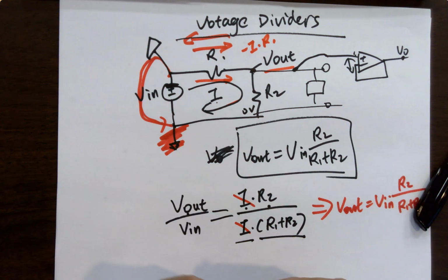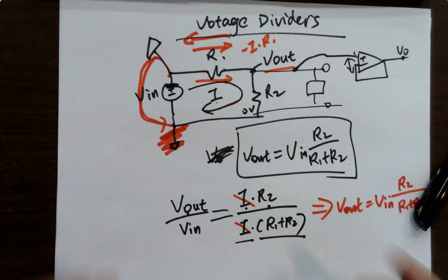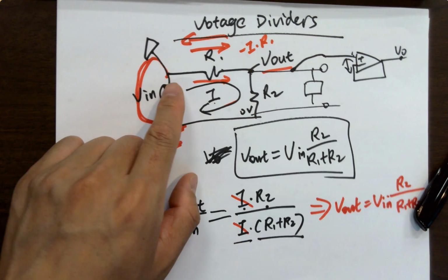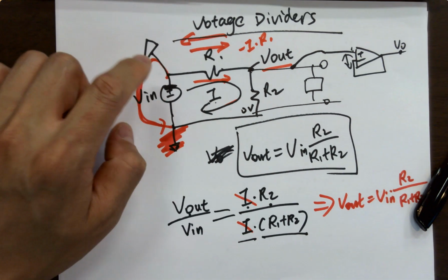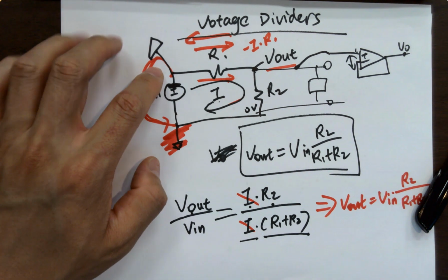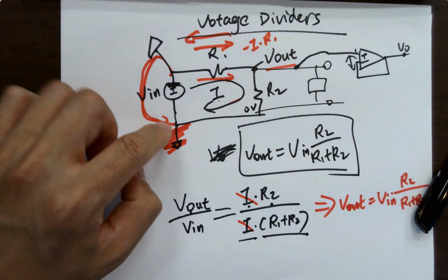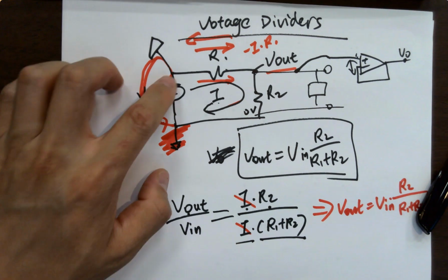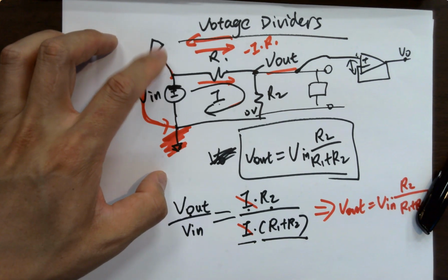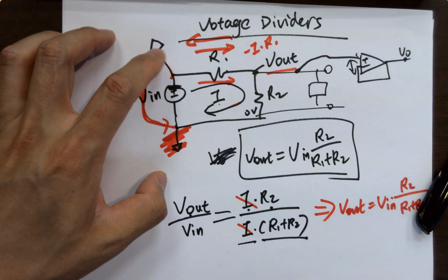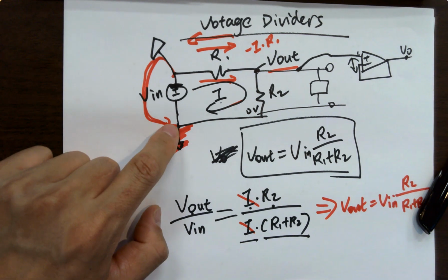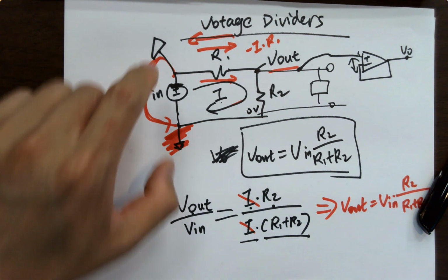Is that confusing? Is it confusing for everyone? Ignore the power source for now. If I ground this power anode, so I grounded the cathode, right? I ground the cathode. Why can I ground the anode? I'm just supplying a negative voltage. It's okay. I ground the anode. What's the voltage here? Is it still Vin? Isn't it negative Vin? It's not negative Vin. I ground it. I told you I ground it. What's the voltage here? 0. What's the voltage here? Negative Vin. Yes. Okay. So 0 volts.